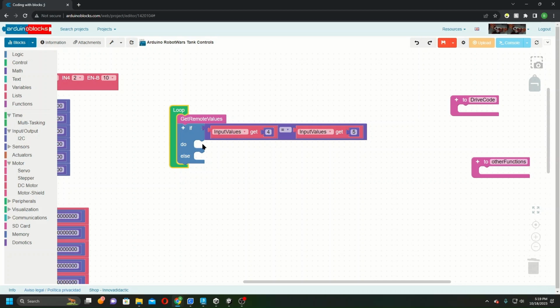However, if you lose communications between the robot and the controller, the value is going to default to 0, because 0, null, is our default value for every variable type. Well, I should say almost every variable type, because as soon as I talk in absolutes, someone's going to tell me I'm wrong. Anyways, if we're checking for an inequality here, this is something we have a little bit of control over, because if we lose communications to the controller, both values will be 0.